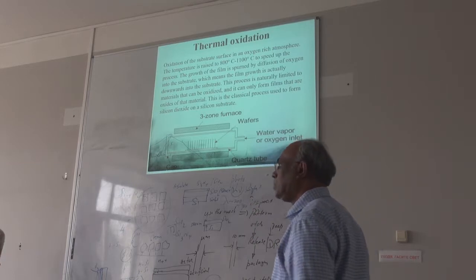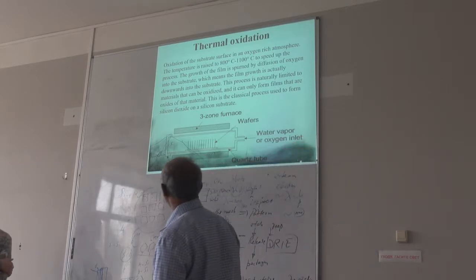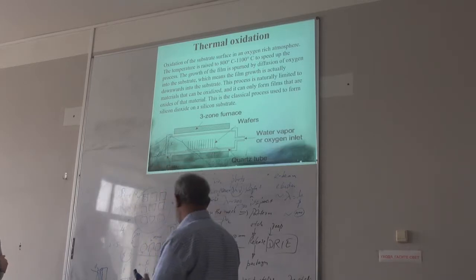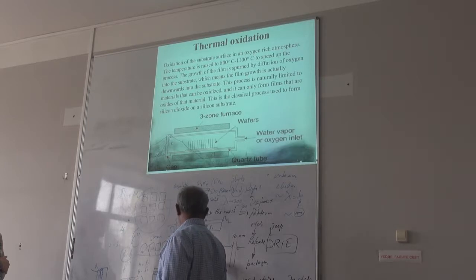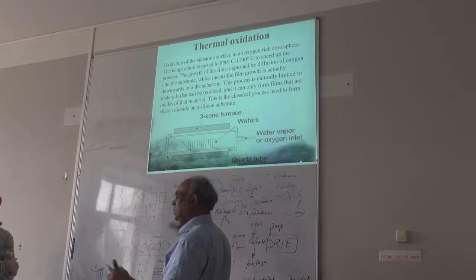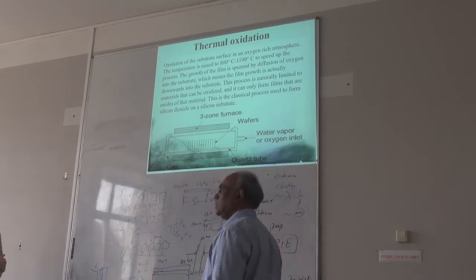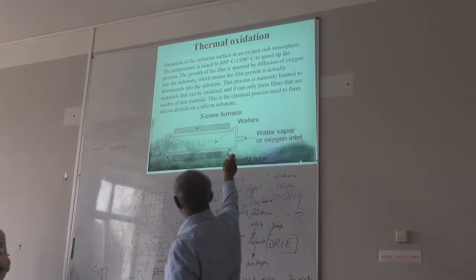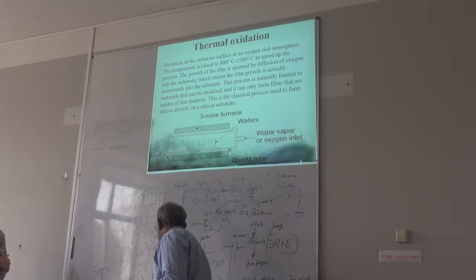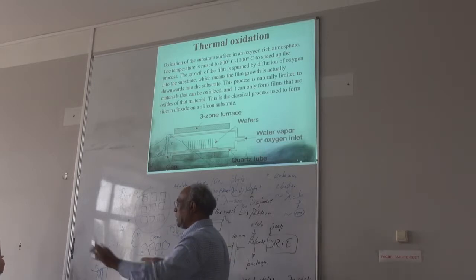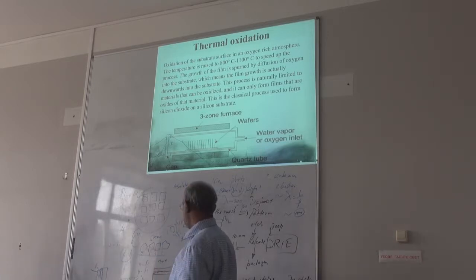And how do you control the temperature field inside the chamber? The furnace has a temperature controller, a PID controller, so you can keep the temperature quite stable. This furnace is already temperature controlled. You have the set point, so you can set it to 1000 or 900 C. You have to wait until it reaches a stable temperature. Once it is stable, then we introduce the oxygen.